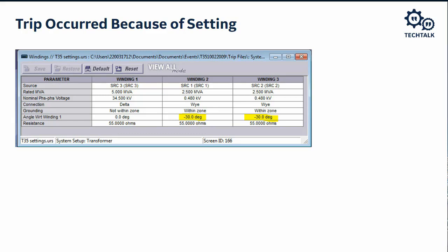That'd be H3. And so what ended up happening here was the strain bus was connected, A phase straight across to the first bushing, B phase, same thing, C phase, same thing. But because of that, the transformers were wired identical on the secondary to CTs, and the relays were wired identical. But because we had wired C phase to H3 on one, and C phase to H1 on the other, and A phase to H3 on the other transformer, we had this phase shift, and that was problematic.